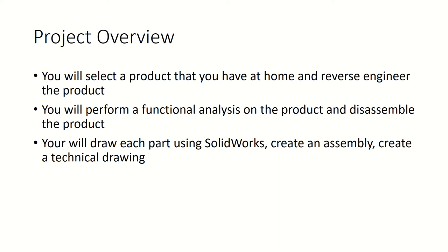When you take the product apart, it will allow you to understand how the product works more, and also allow you to measure each of those parts so that you can actually draw them in SOLIDWORKS. And so after you take it apart, see what all the different parts are, understand how they function together, how the system works, then you'll use SOLIDWORKS to draw each part, then create an assembly, and then you are going to create a technical drawing of the assembly.